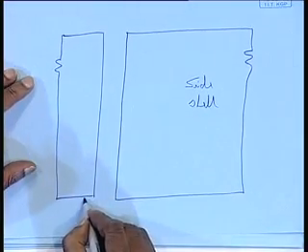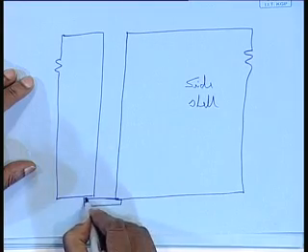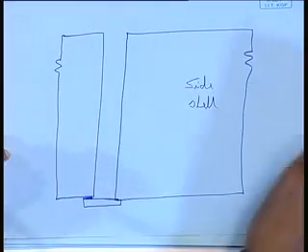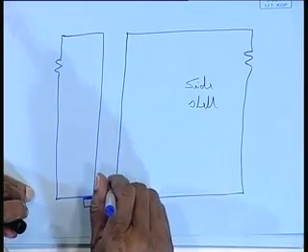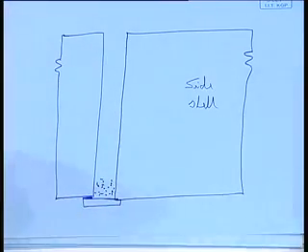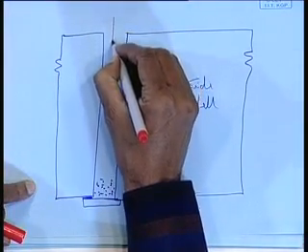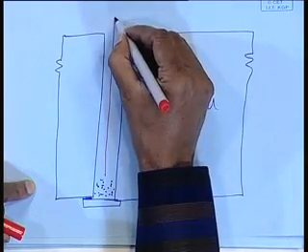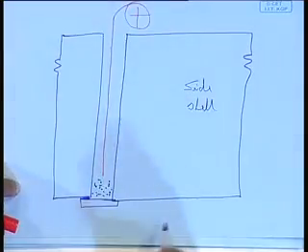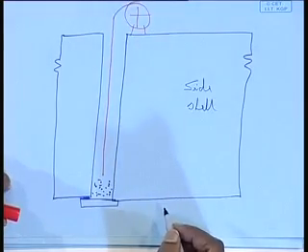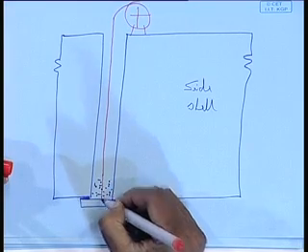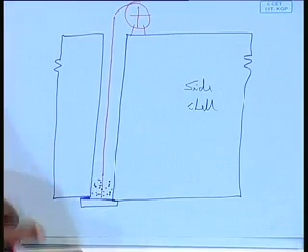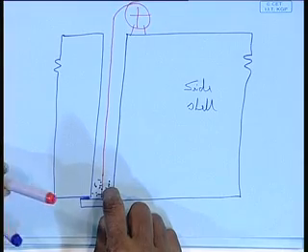So, here if we think of a situation like this, this is my backing plate, and the so called granulated flux is poured here at the beginning, the starting point, right, and you have the electrode. I have a mechanism through which I can put the electrode down from a spool at the deck. Imagine such a situation, the electrode is coming down, it comes and strikes an arc at the bottom. Initially, it strikes a normal electric arc. In that arc, this flux melts.